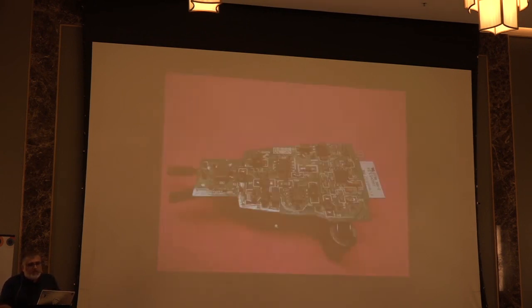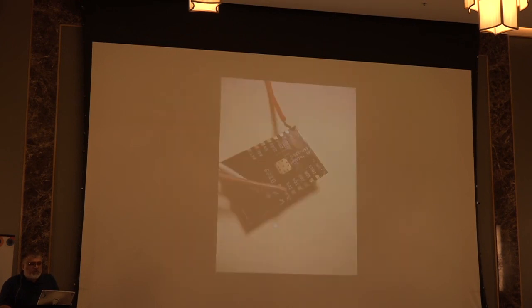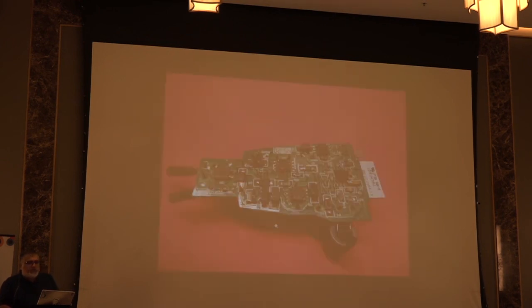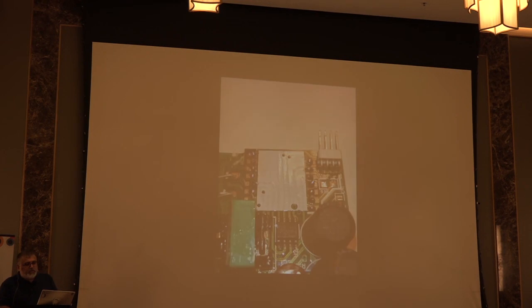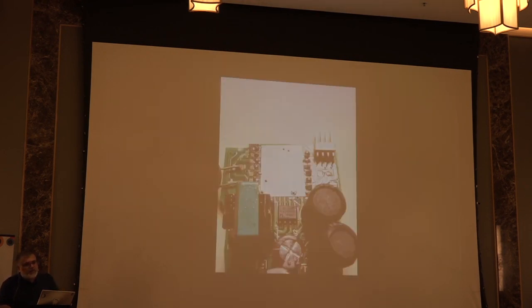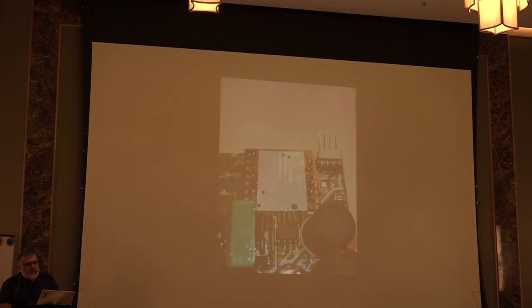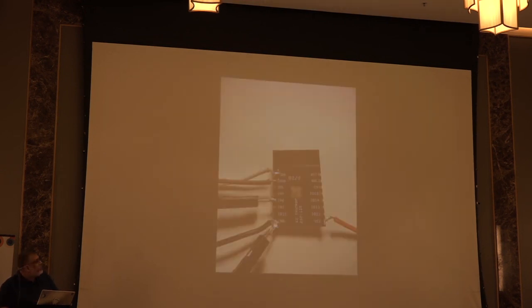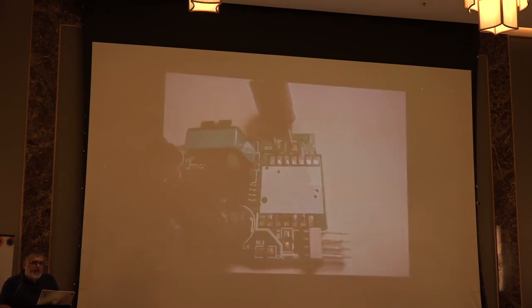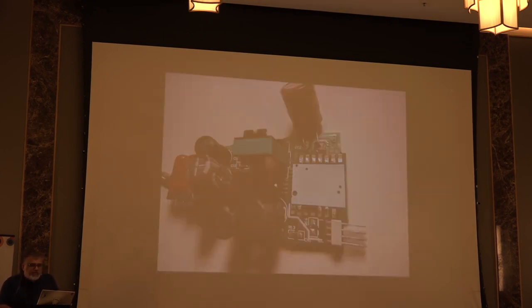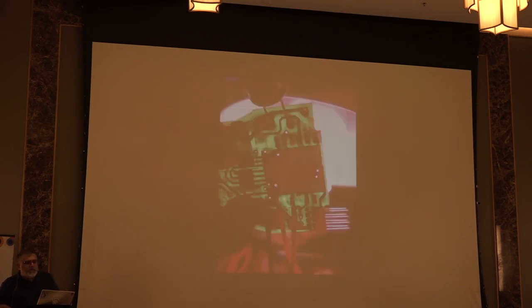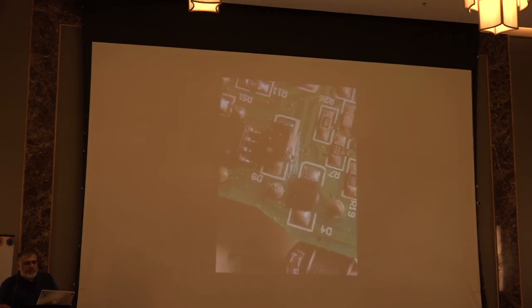Now, here I again could not program the microcontroller the way it was plugged into the board on it. And this time what I did is, I took another microcontroller, this one, an ESP8266. I programmed it, and then I soldered it directly onto that board. I made a few mistakes.